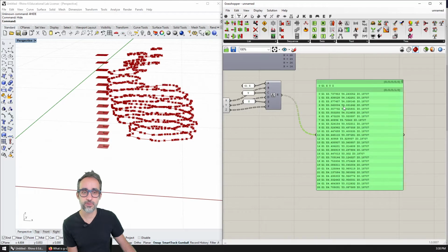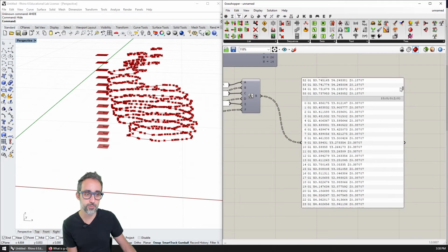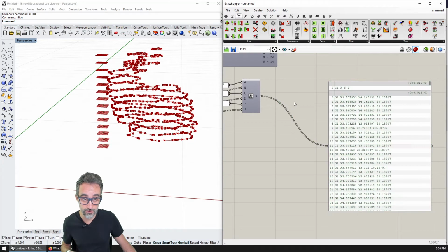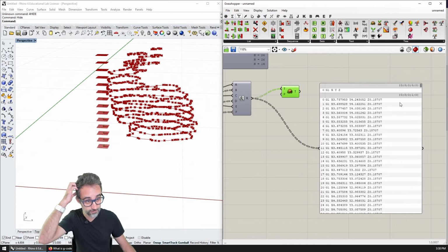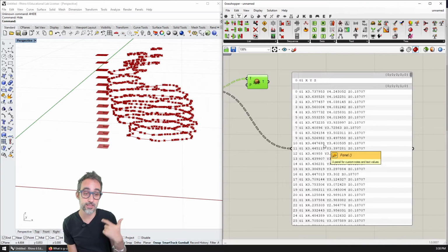When we create a G-code program, we don't really need all the branching instructions, correct? So I would need to eventually, at some point, flatten all this information whenever I was ready to send this to the printer. However, in this case, it would be super interesting to maintain the branch instructions, because at some point we also need, as part of the program, to make